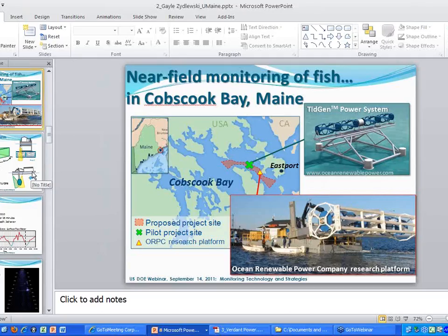Was there a second question there? Oh, the rotational speed. So I think the tip speed ratio is about 1.5, or the optimal tip speed ratio. Okay, that's fine. Peter, do you have more information there? Yeah, it runs about a revolution every second is about right. A little bit slower actually. And it's dependent on the tidal current.